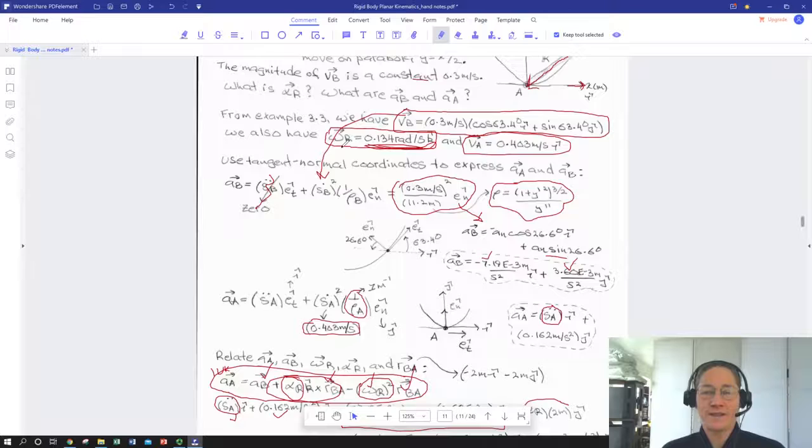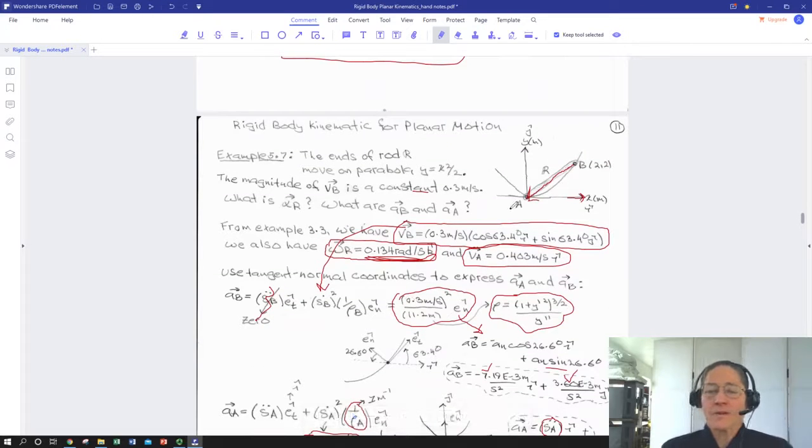So key points here. Recognizing first of all what we had and what we didn't have. And it's interesting that, this is a note, if we know something about velocity and we know something about relative position, it's useful to go ahead and solve for everything we know, especially about the angular velocity of a rigid body with respect to our reference coordinate system, because we know that's going to be one term in our acceleration that we'll need. So go ahead and do the work with velocity first, then see what we need to do for acceleration.